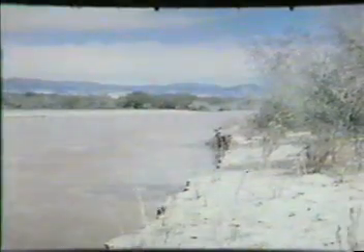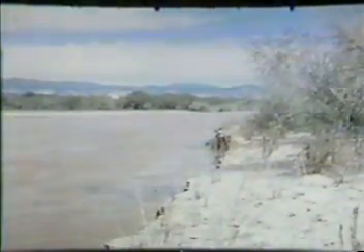As illustrated, more than one form of bed roughness may exist in a reach. Here we have standing waves, anti-dunes, and plain bed in the same reach. It is entirely feasible to have standing waves and anti-dunes in the middle of the stream, plain bed adjacent to the standing waves and anti-dunes, and dunes or ripples adjacent to the plain bed. In this situation, the resistance to flow is a function of the area of the total bed occupied by each bed form.